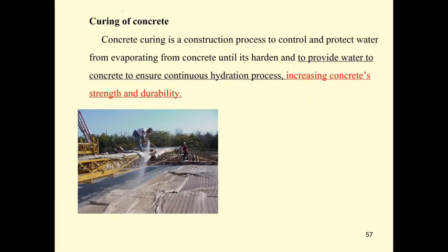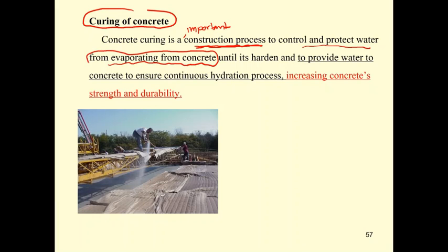Now is the time for curing the concrete. Concrete curing is a very important construction process to control and protect the water from evaporating from the concrete, so we don't let it go away. The hydration process will then have water to react and harden, and curing also provides water to the concrete to ensure a continuous hydration process.